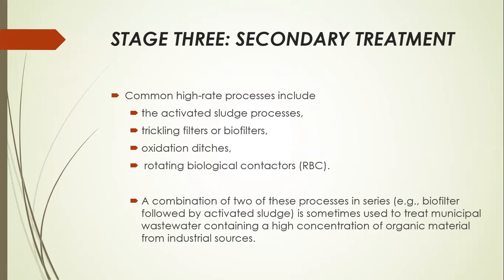And you can see the trickling filters or biofilters. And again, you have other variants such as oxidation ditches, right? That is again a suspended growth process. And also you will see rotating biological contactors.